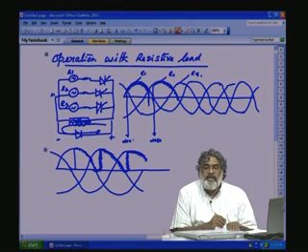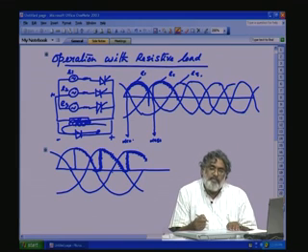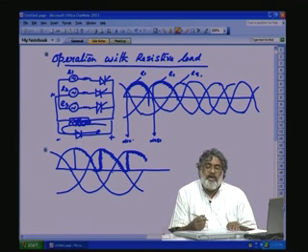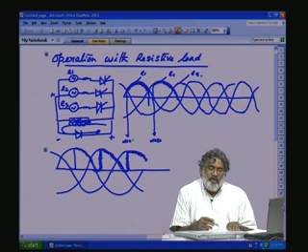Okay? This is possible. So, this way we can ensure, suppose we want to limit the output voltage, we do not want the output DC voltage or instantaneous voltage to go negative, we can use a freewheeling diode. And with the firing angle variation, we can have an output voltage variation from 0 to positive.